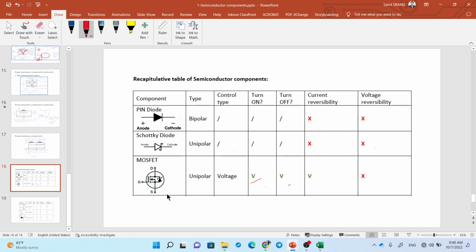Let's say the potential here is higher and here is lower. For example, you reverse the polarity of the battery like this, and this battery is 12 volts. If you didn't have this diode that allows the current to flow this way freely, it would block the current, then the voltage here is the same as here, 12 volts. So it would have reverse voltage, right? But you have a diode here, then the current can flow freely. So there's no pressure, no voltage.